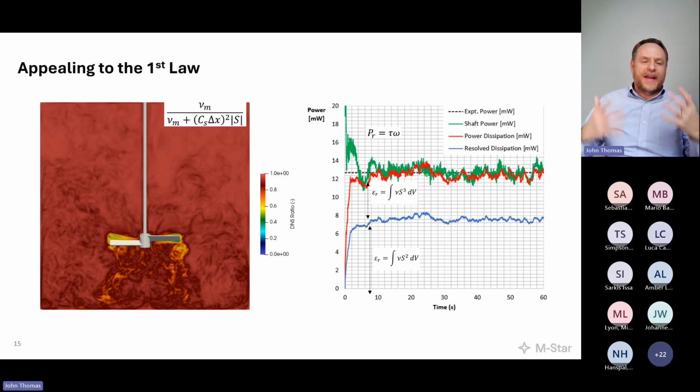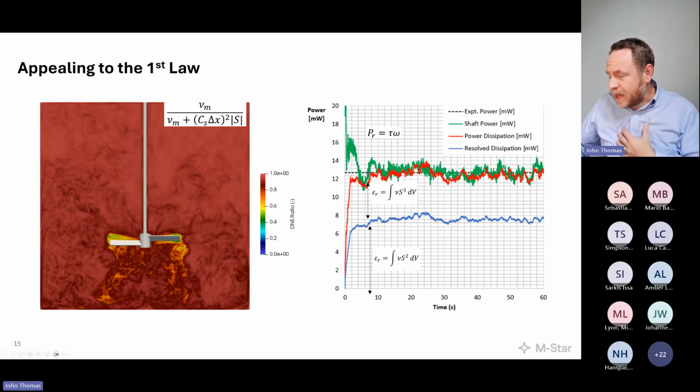That's where the subgrid model has to do its thing, because that's where a lot of these small eddies live, as it were, that aren't being captured explicitly by just Navier-Stokes, that is said to be topped off by the subgrid model. It's kind of cool to see that net effect, both in terms of the total energy dissipation as well as the local effect of the algorithm. Again, I'm kind of peeling back the curtain here.